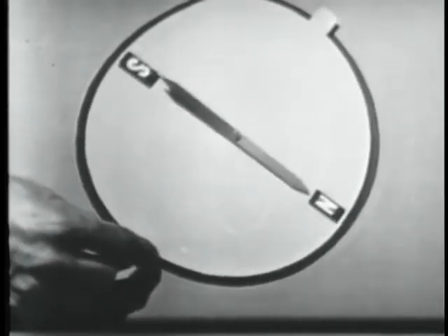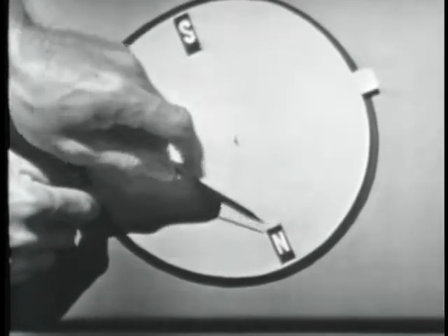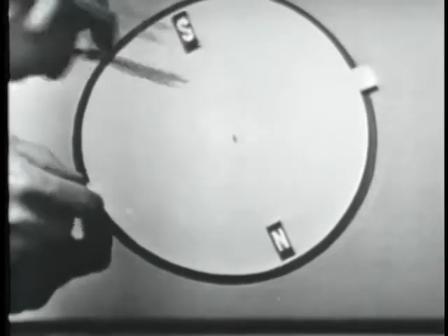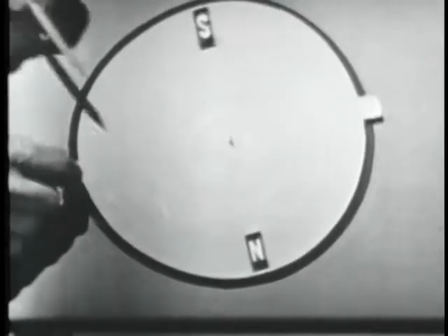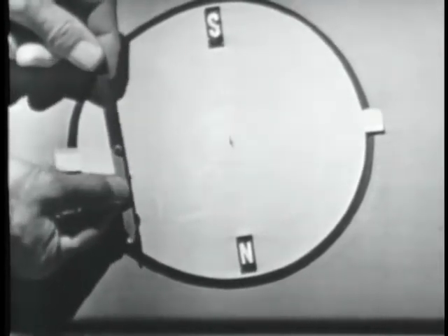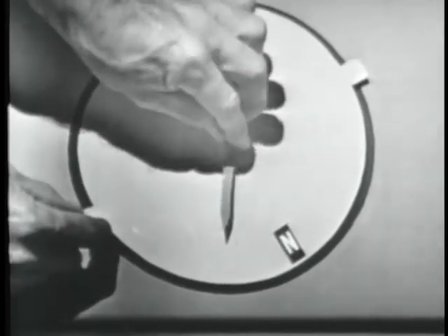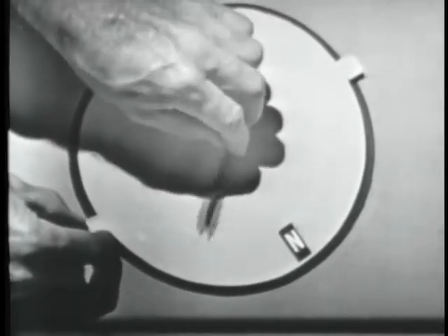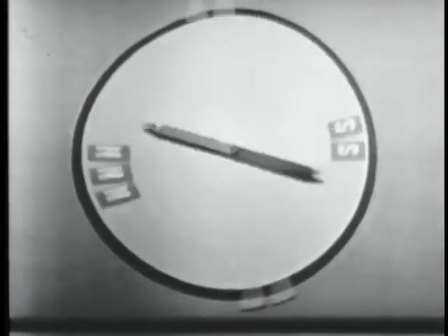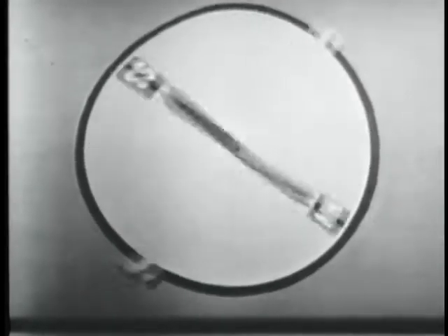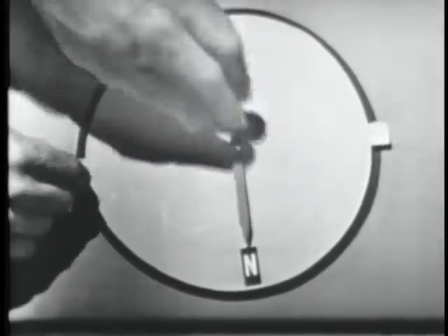Okay, what we have here is a cardboard disc, mounted on a pivot, by the way, so that we can spin it, and we have 2 permanent magnets glued to the disc. Thus, if we spin the disc, we have a rotating magnetic field. Now, the principle we want to show you here is that if we take another magnet, such as this compass needle, and put it on the pivot, so it's free to rotate, and we spin the cardboard disc, we have a rotating magnetic field. Now, you'll notice that the compass needle picks up the rotation of the rotating magnetic field, tries to align with it. Now, this is an extremely important principle.